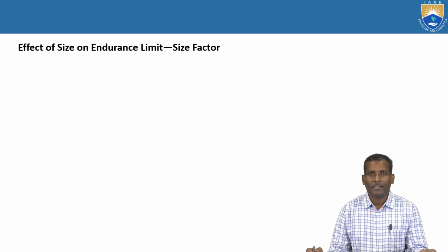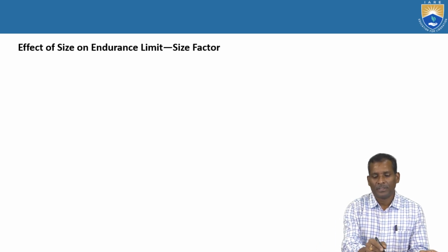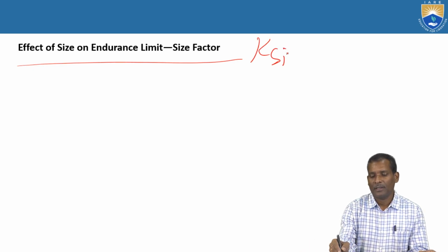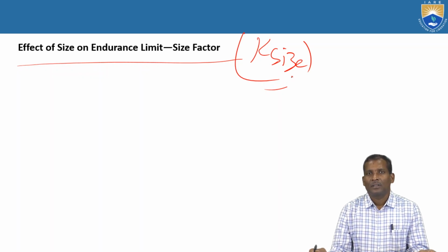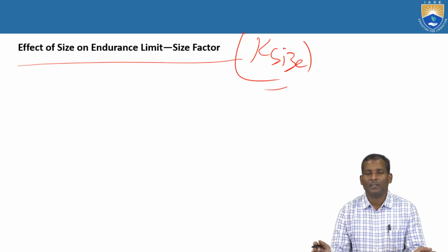One more factor is there, that is the size factor, the effect of size on endurance limit, K size. The endurance limit value depends upon the component size. Suppose your specimen dimensions are very large.